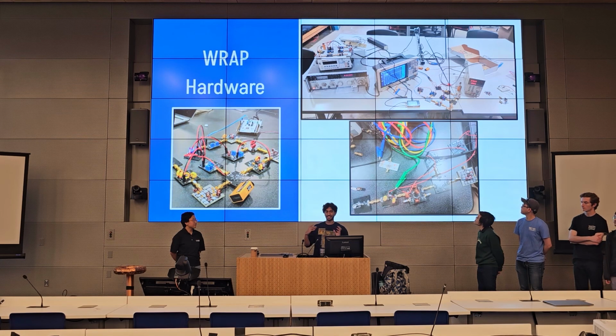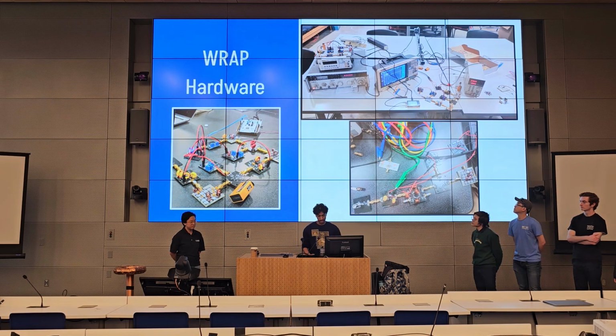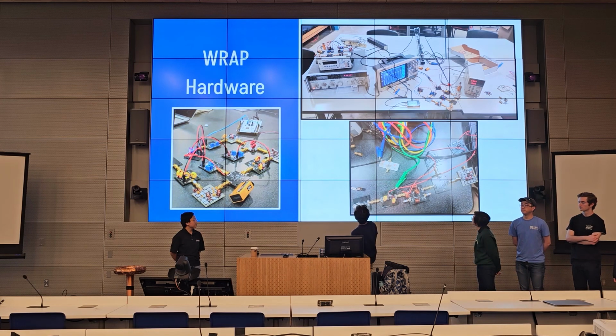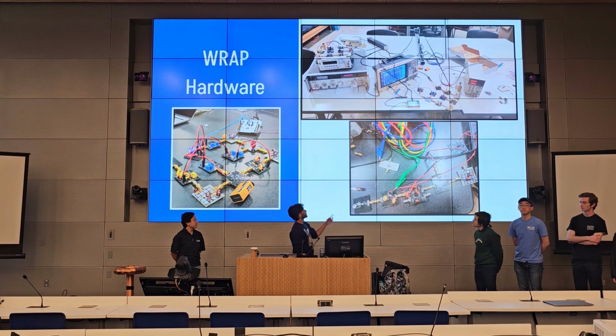Well, we actually have lectures that go through all the theory and the applications, and we'll give you a module after that that will walk you through what you need to do to get a realizable module. So over here in the top picture, you can see us testing out the transmitter, and it's basically all modular. You can see that we have an amplifier, a filter, a mixer, then we filter, amplify, and then output. And we can bring that into a spectrum analyzer.